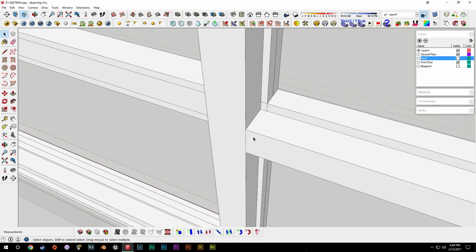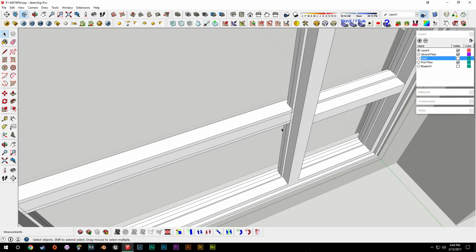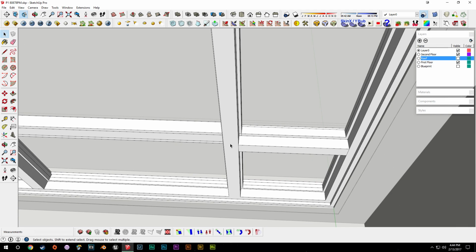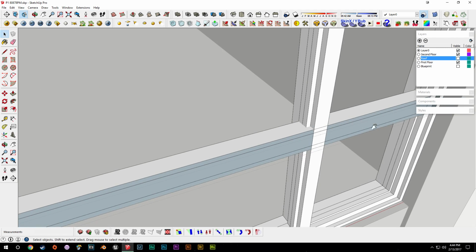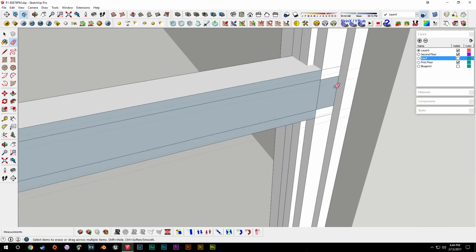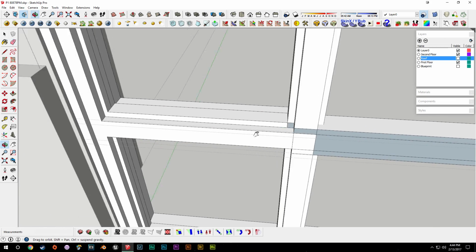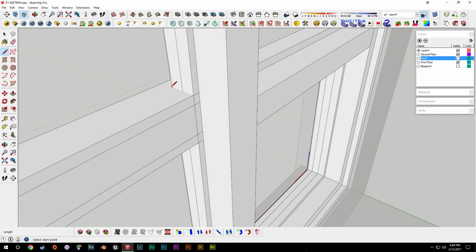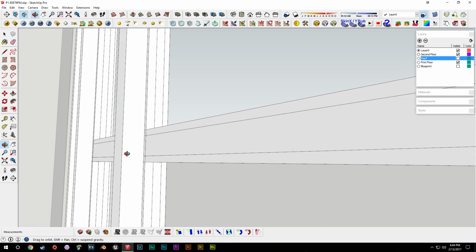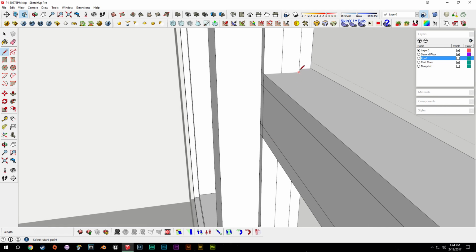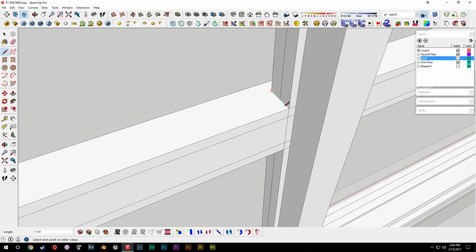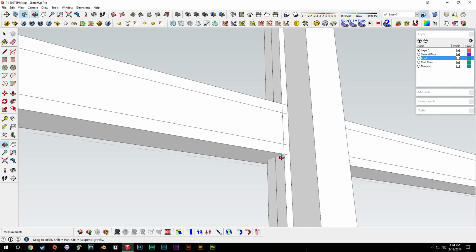And this one's going to be a little trickier because we have these crossbars going down. So we're actually going to have to pull this through for each individual one because it's intersecting with the front piece here. And so it'll take a little bit extra time, but it still sort of operates the same way as the rest of them. So I'll actually draw these lines in, top and bottom here, and that will allow us to erase some of these extra lines without it erasing faces. And then we can just pull these through without having to pull all these individual squares through as well.